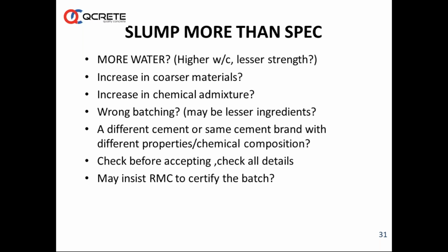There are a lot of variations that happen, and it is sometimes a nightmare for QAQC people in the ready mix companies to deal with different brands of cement, and some brands of cement coming from different plants. So these things have to be taken into account. Check before accepting.